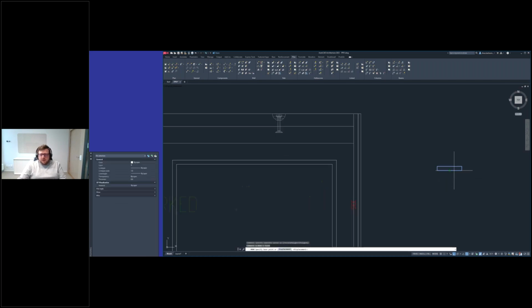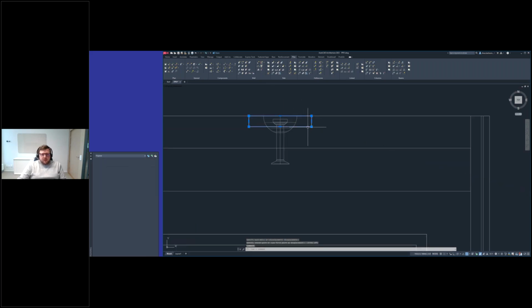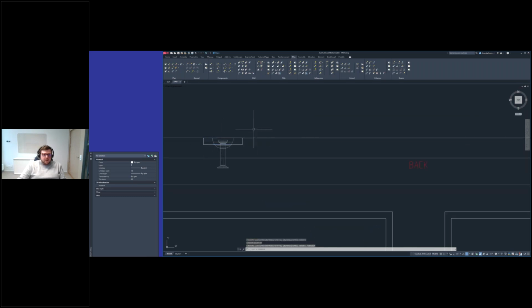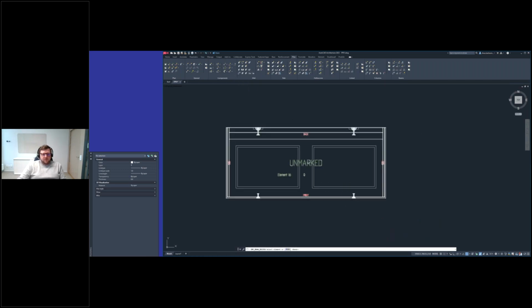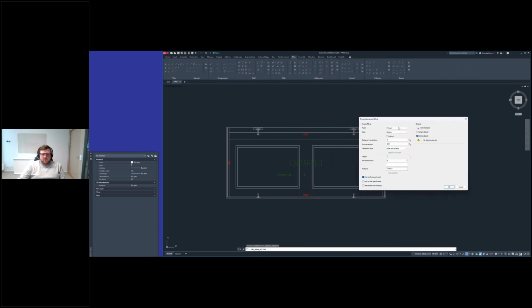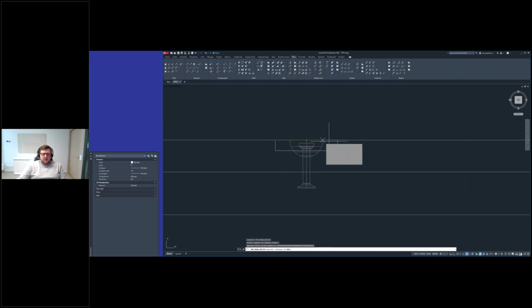So I have a template to make stuff easier for me. So I'll just take it there and copy it to there. So first thing I will do is the recesses. So I will draw my recess. I will do it on the element that's the start. I will come and make a rectangle one from top. I want to have it 200 millimeters, and yeah, say okay, and just draw it like this.